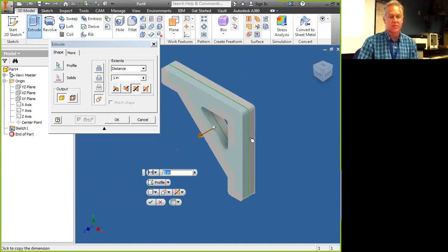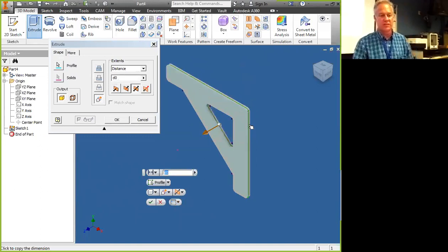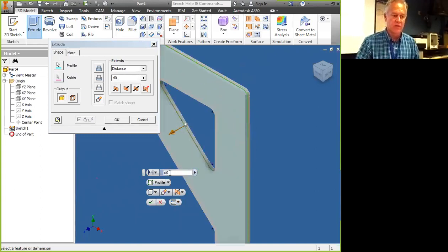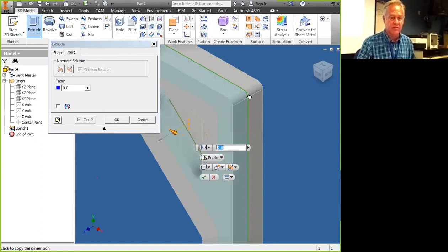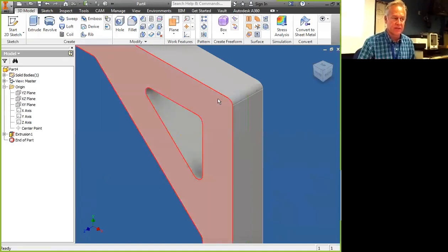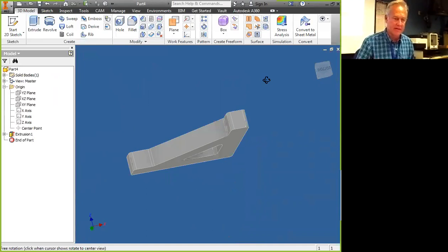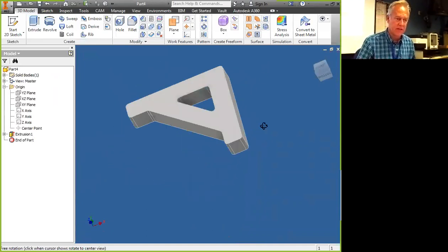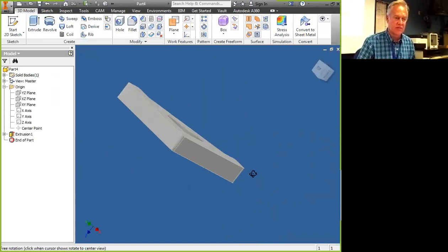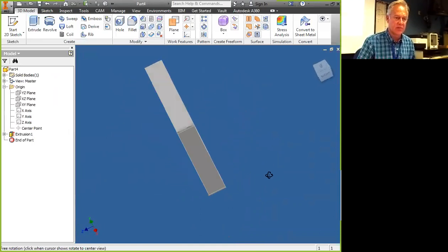In other words, the geometry that you see that came with the AutoCAD sketch, we're going to make it symmetrical about that axis to 1 1/8 inch in size, just like so. And now you have a fully constrained 3D sketch of an angle bracket.